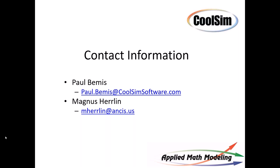Michael Green asked, when leakage was repaired, I would expect the PUE to become more efficient. Is that a faulty assumption? Well, the problem, Michael, is that PUE is not that sensitive, unfortunately, to changes like that, because it has IT energy in the numerator, and the IT energy tends to wash out improvements you make to cooling energy. I'm not a fan of PUE for that reason. It's fairly insensitive as a metric. MLC is going to be much better, but it hasn't caught on.